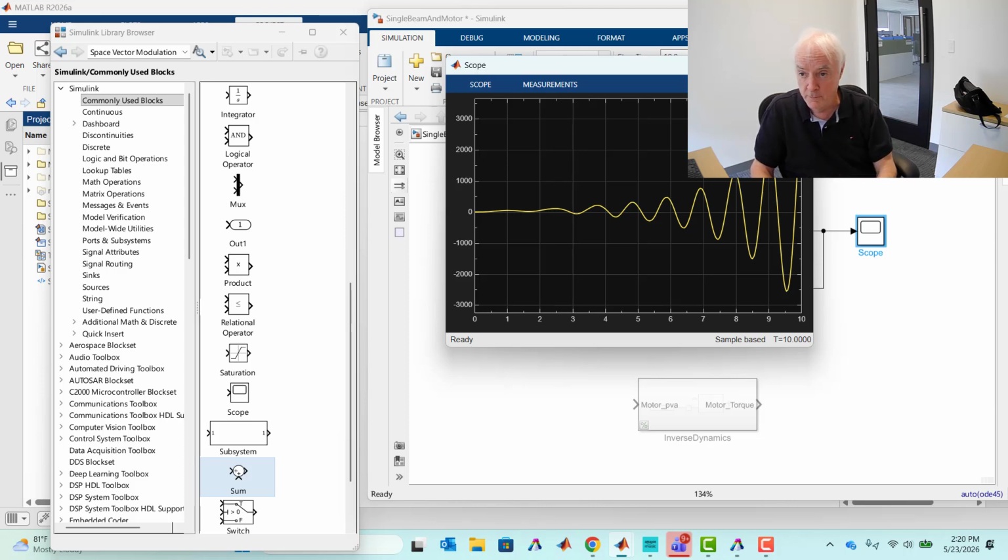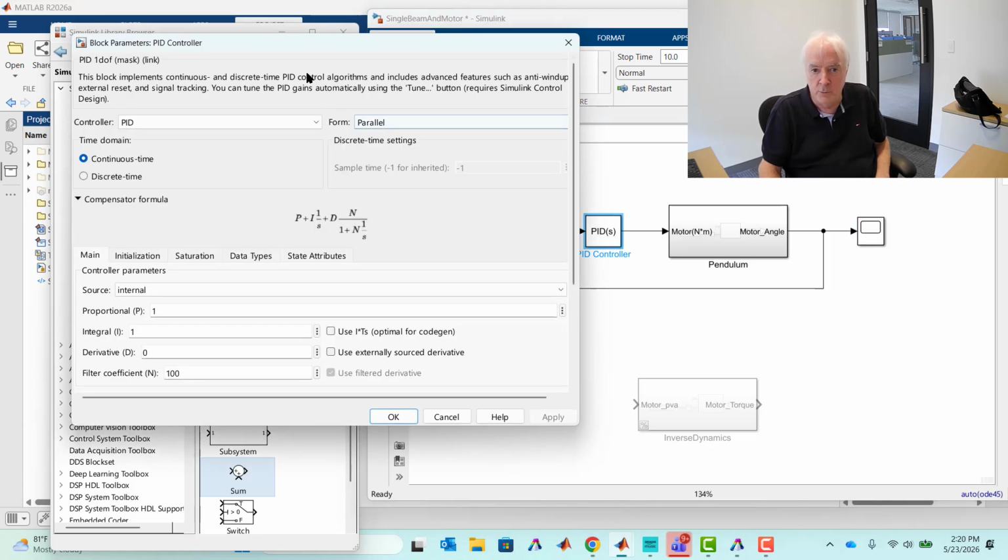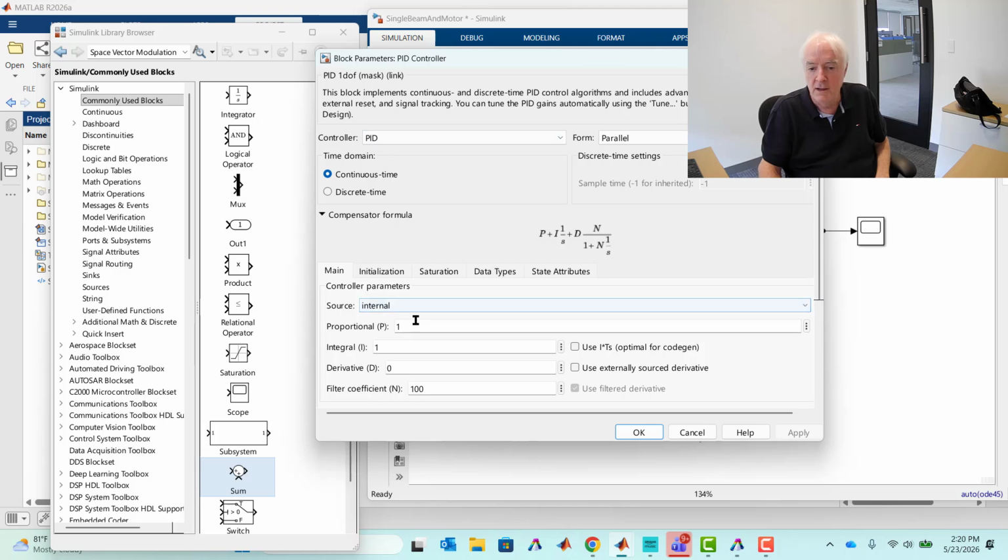But one of the really important points about mechanical motion control is your controller needs to understand at some level what it's controlling. All right, and so even PIDs with feedback operate with an understanding, and it's through what we call tuning that they do this. So it's an empirical kind of understanding that will get expressed in the constants that drive the